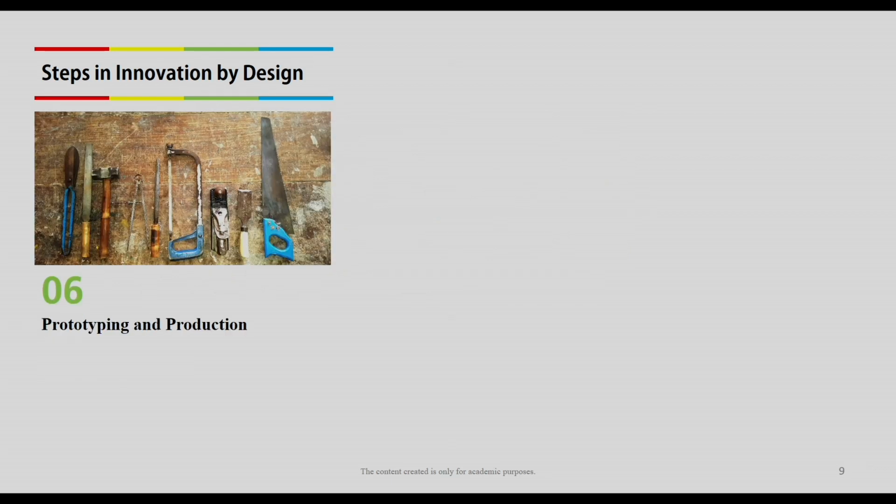The next phase is prototyping and production. The final concept is further modified according to material and manufacturing limitations. A designer then makes CAD models, mock-up models, functional prototypes to get feedback from the user, based on which further modification is done. After selecting the final prototype, the design goes for production. So, here the process is very iterative.